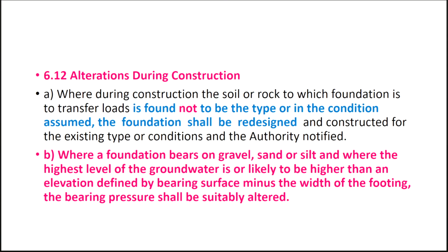Possibly the plan area of my footing may be 2 meters by 2 meters. Then if the bearing capacity is reduced by 50%, possibly the new dimension may be 4 meters by 4 meters or 3 meters by 3 meters. So please get it redesigned. This clause is very important: in case during construction the soil or the rock for which the foundation is designed is not found to be in the condition assumed, the foundation should be redesigned.